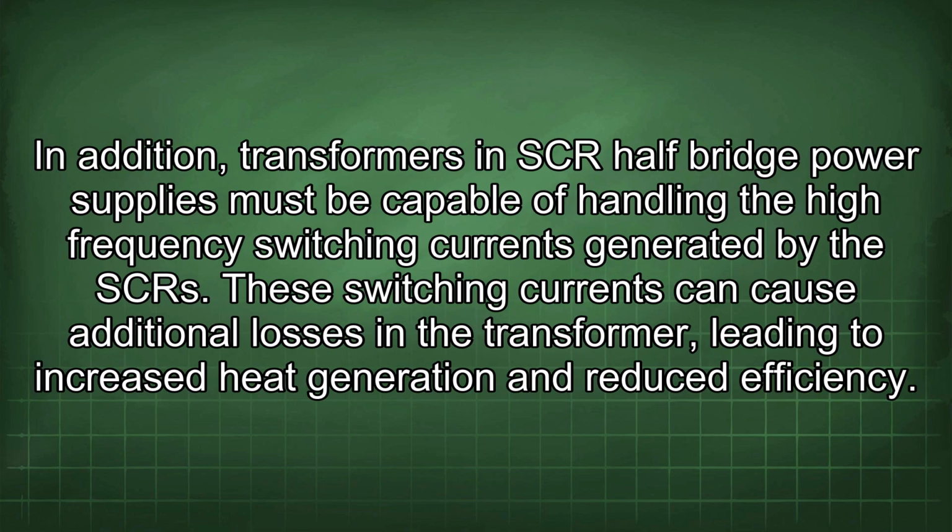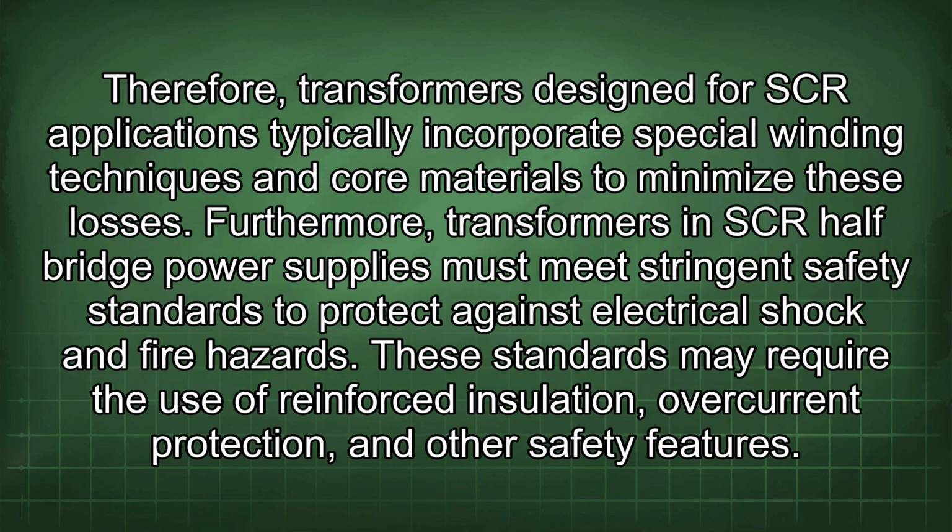In addition, transformers in SCR half-bridge power supplies must be capable of handling the high-frequency switching currents generated by the SCR. These switching currents can cause additional losses in the transformer, leading to increased heat generation and reduced efficiency. Therefore, transformers designed for SCR applications typically incorporate special winding techniques and core materials to minimize these losses.